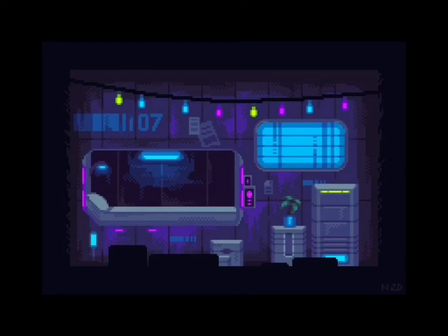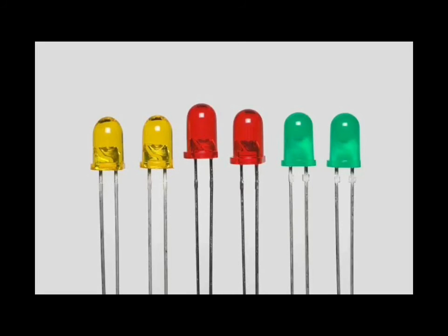Here are some applications of the series-parallel combination circuits. LED. Electronic components that emit light when a voltage is applied are often arranged in parallel and in series. One advantage of arranging LEDs in parallel is that when one LED light goes out, the rest will stay lit. In a series LED arrangement, when one light goes out, so will all the rest. Series LED arrangements, however, require less electrical current to operate than parallel arrangements.